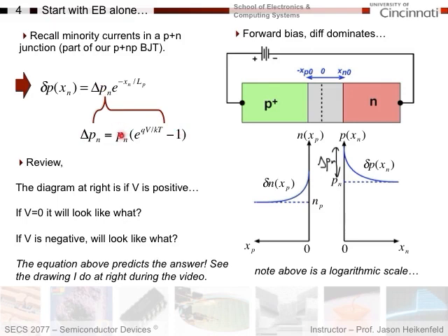It's P sub n, the normal concentration at thermal equilibrium, and then this part of the diode equation, which says that if you go to forward bias, it'll go up, as you can see here, and if you go to reverse bias, this term disappears. I have minus 1 times that, meaning that it will go to 0.